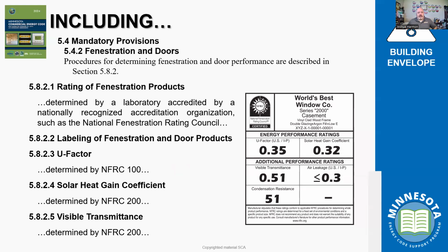What we're doing as inspectors maybe is going out saying, is the right window in the right spot, right? Or maybe there is a commissioning agent, depending on our compliance path. There's somebody going out, a VPT, verification and testing provider, going out and saying, yeah, we double checked. They put in the right windows, right? That they were properly flashed, and we had the right air leakage and U factors.